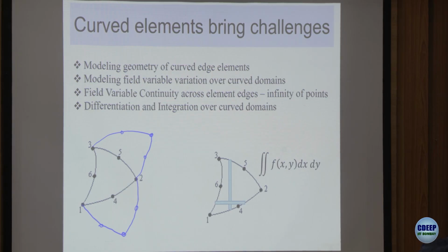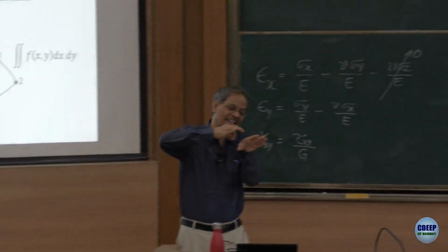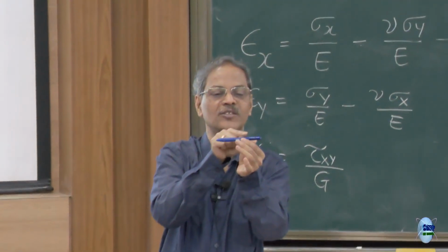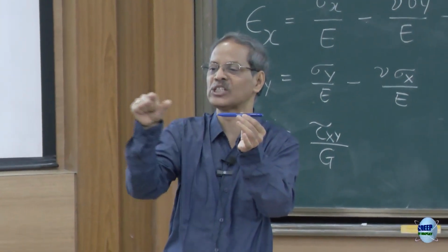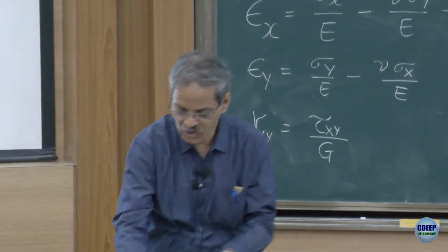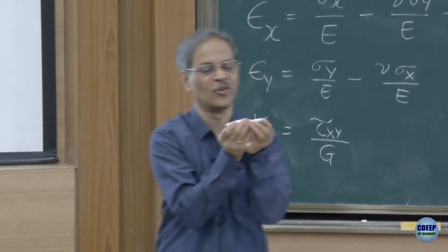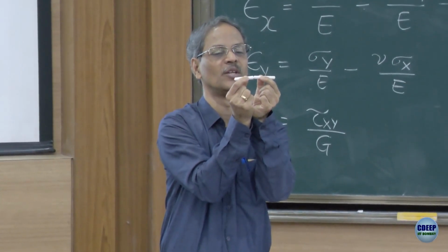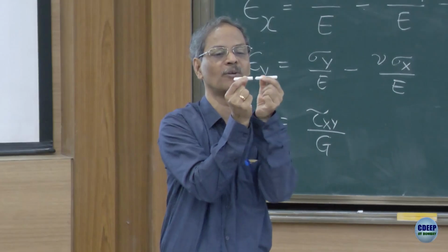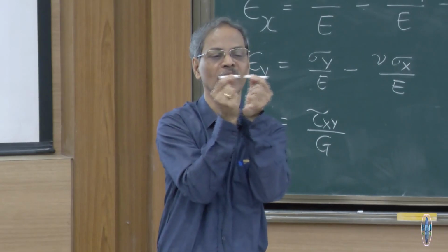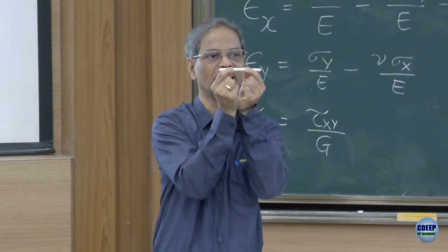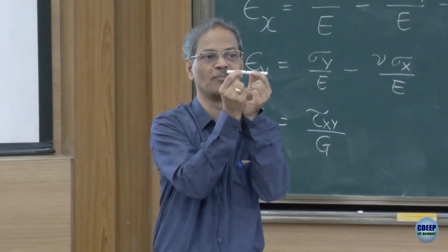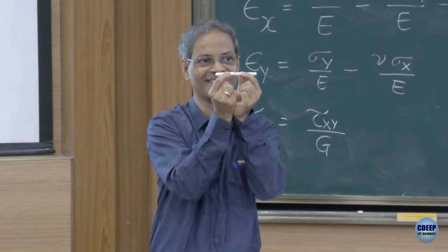When they interface on any edge, in the one-dimensional case, there were line elements, and two elements were meeting only at one point. So if the field variable, temperature for example, at this point is 102.84 degrees, whether you come from this side or this side, you are satisfied. It's a unique number, whether you come from left or right, and it's therefore continuous.